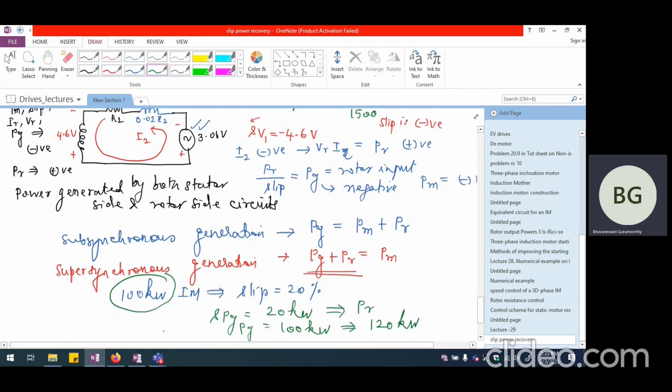That is one thing. And the second thing is, in both subsynchronous and super synchronous cases, the generation could happen depending upon the range of slip for which I have designed the entire generating system. So at subsynchronous generation, the generated power may be a little lower, whereas at supersynchronous generation, the generated power will be higher than the rating of the induction machine itself. So this essentially is an introduction to using a wound rotor induction machine for wind energy conversion system.